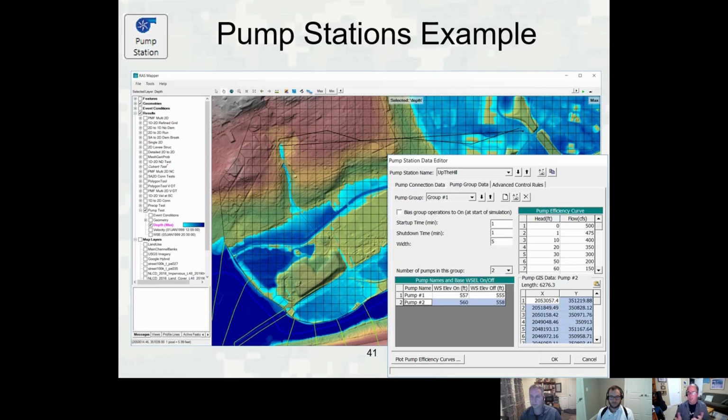And then what you're going to see is you either need to drop the time step, if you want to keep the cells the same size, or you need to make the cells larger so you can keep the larger time step. Yeah, even just that one cell where the pump is drawn out of, right? Because then you have more storage, and so it's less likely to draw out. Absolutely. So it could be a situation where maybe you just go through and manually remove some of the vertices or the points around that 2D area to make that cell itself a little bit larger.